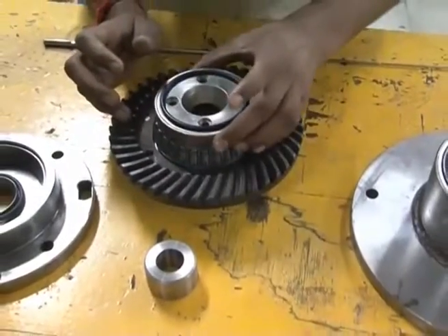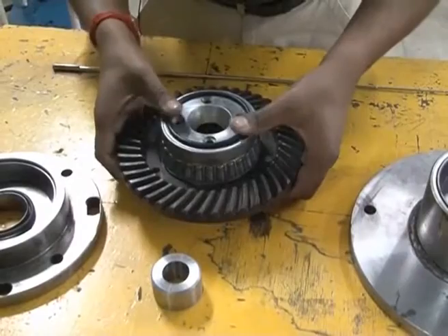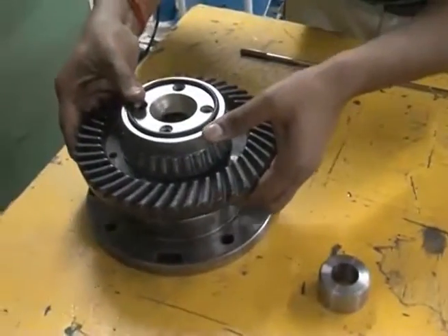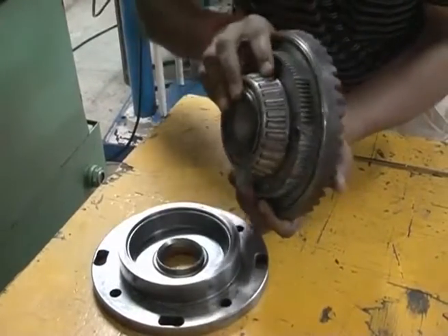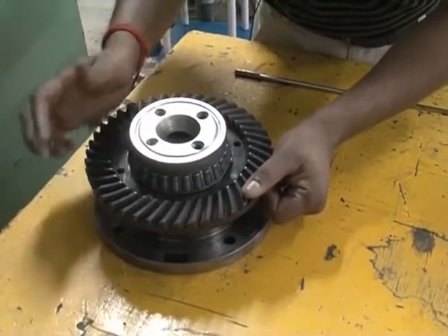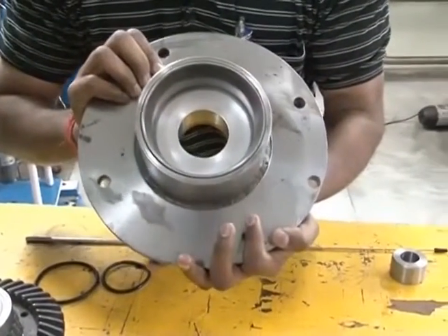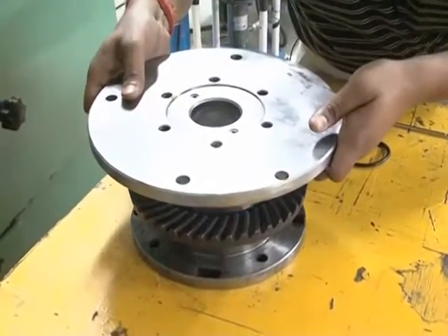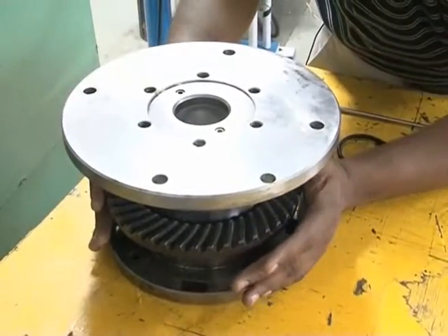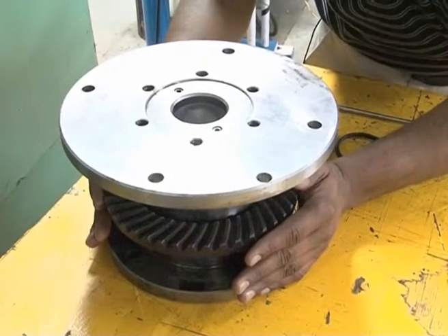This is the locking plate, and we have 4 screws to tighten it, and we place this total system in the bottom plate. There are 2 ball bearings. This is one ball bearing and another one is the top ball bearing, in order to give free motion to the workpiece. This is the top plate to cover the complete tooling, and this will go and sit like this. This is called the complete rotational tooling for the universal rotational abrasive flow finishing process.